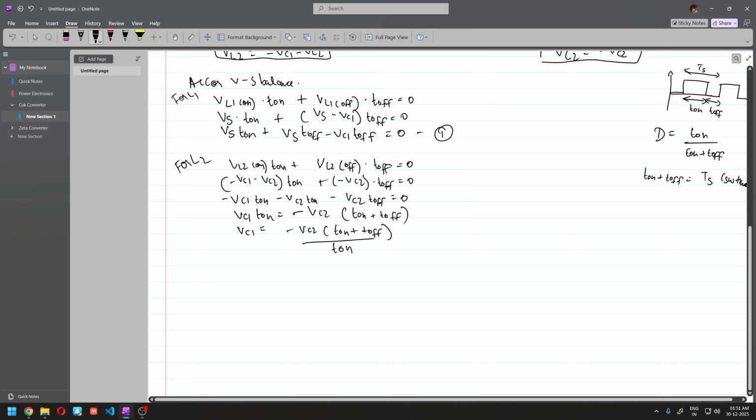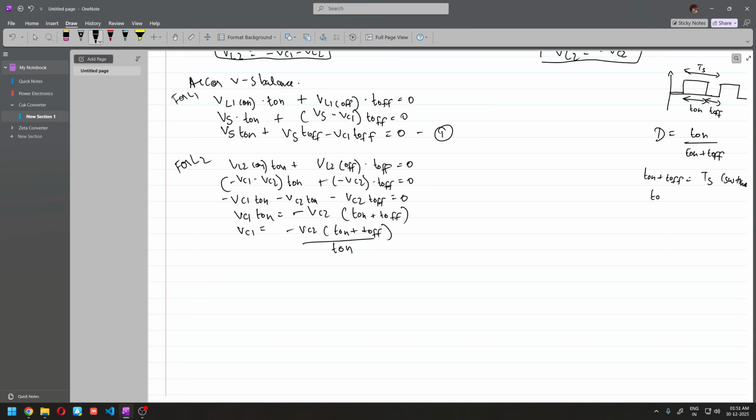So this is your switching time, and just rearranging this equation, T on will basically be duty times your switching time, whereas T off will be 1 minus D times switching time. So these are fundamental equations. They always help in writing, because if the duty is say 40%, in numbers it's 0.4. So the remaining off time has to be, because 100%, or 1, is the maximum duty, so the off time will be 1 minus D times the switching time.